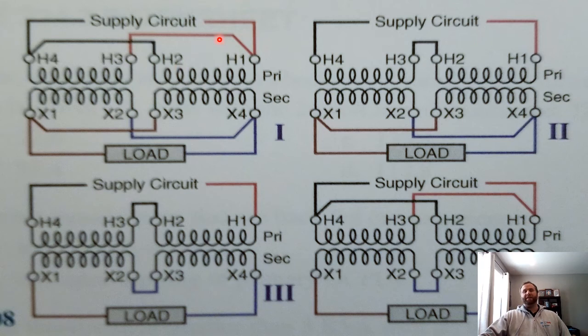And if I apply this to a single pole breaker, I would use diagram I here. Again, 120 each winding. If I applied it to a 240 breaker or a 2-pole breaker, each winding is still rated at 120, but I add them together by putting them in series in order to get my 240. You will need to know the relationship of series and parallel circuits for this exam.